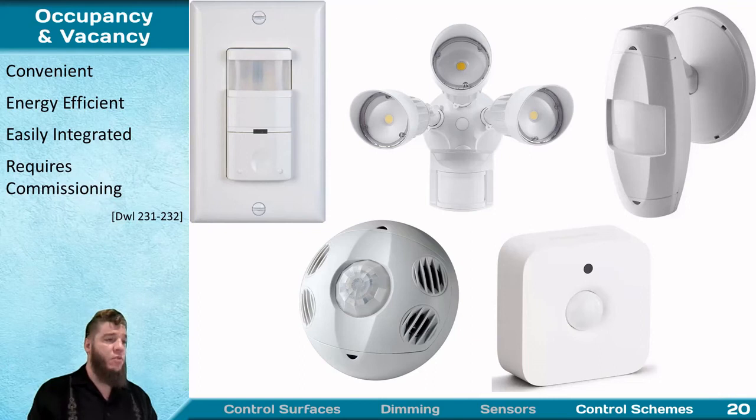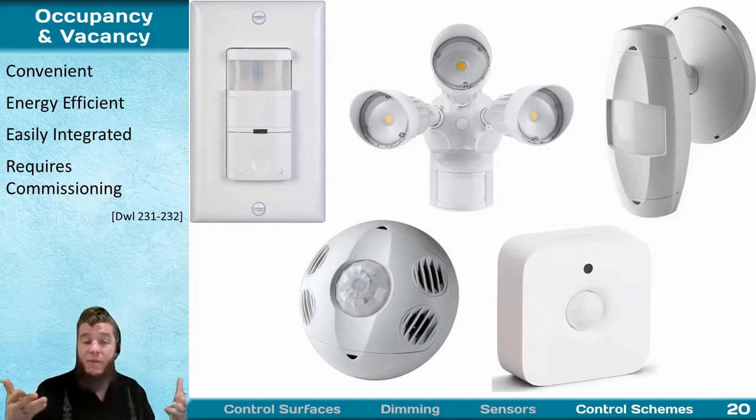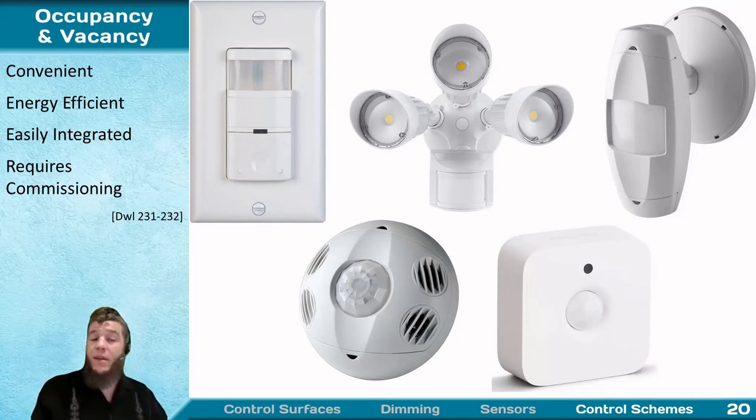And you can dramatically increase the reliability and reduce the number of false positives and negatives by using a networked sensor array. So that's becoming more and more viable as we more and more often load these types of sensors into luminaires themselves. An LED luminaire already has a microcontroller on board because it needs it for the driver. So there's no reason for it not to also utilize a sensor and respond to the sensor's inputs. And if you have a whole series of these luminaires inside your space, there's no reason you can't network the whole set of luminaires and get a ton of information to make decisions on.